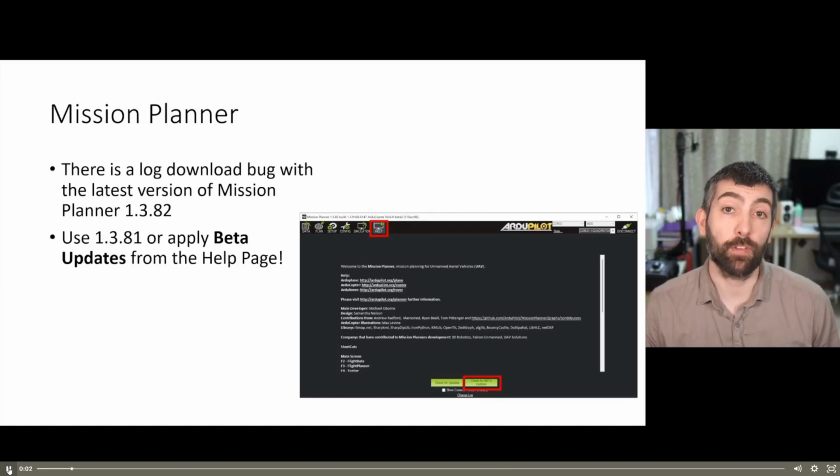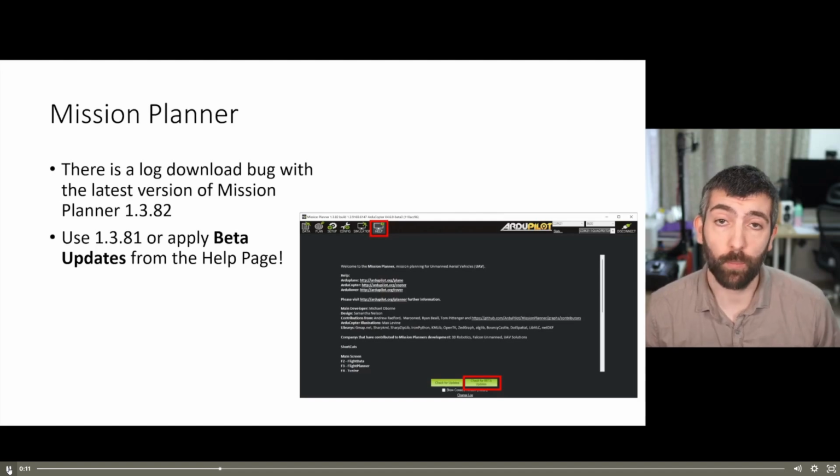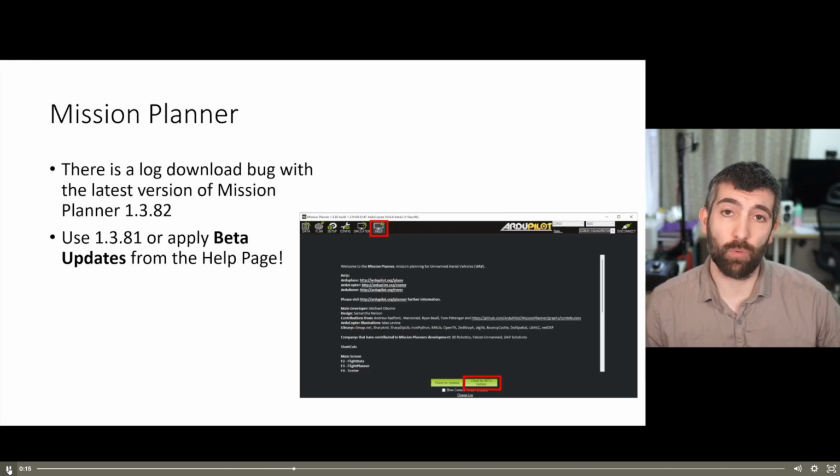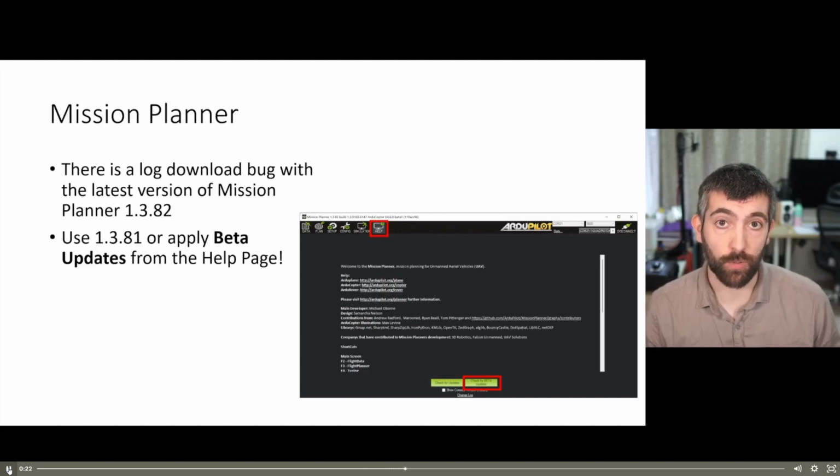There's a link down in the video description to where you can download Mission Planner, but you should be aware that there is a bug with the latest version of Mission Planner as of the time of this recording, which is 1.3.82. And that bug basically makes it impossible to download logs from the drone over USB. It's just incredibly slow. It's basically unusable.